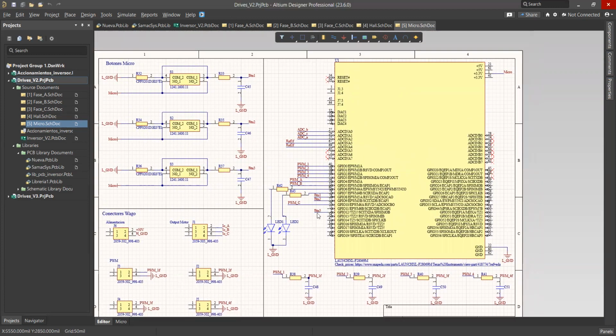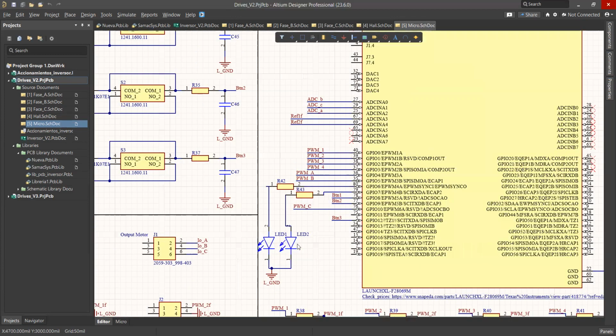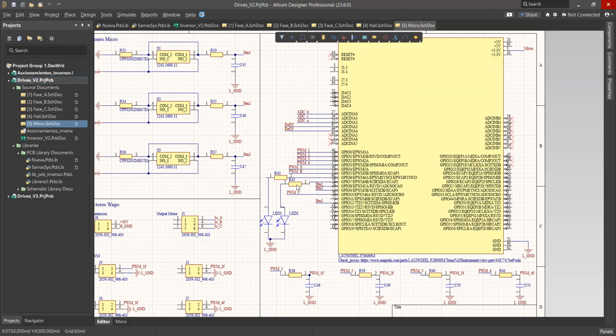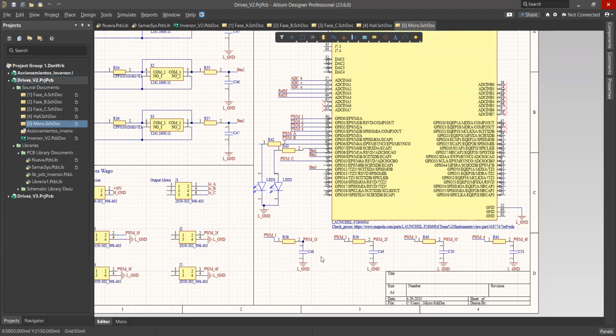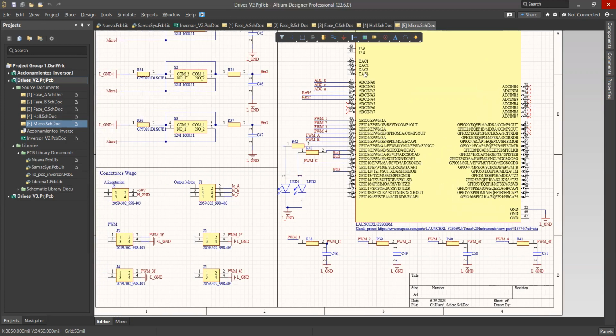These button signals are processed in a digital way, and then we can control two LEDs in order to indicate which operation mode is being held. Also, we have as output four PWM signals that are as well filtered with a low pass filter, and this output will help us to make some extra measurements.